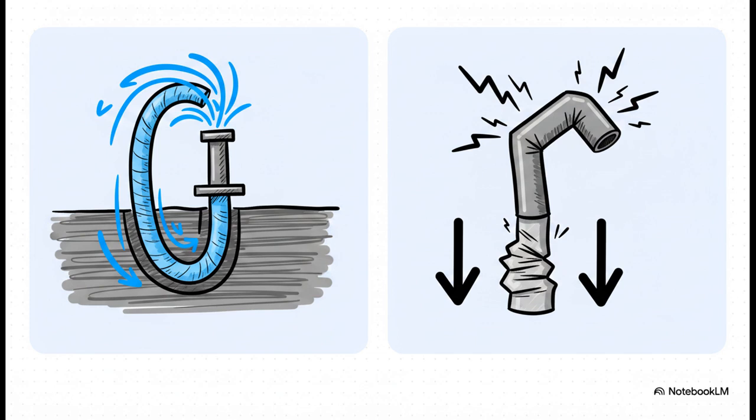But the cons? Well, bending solid steel onto a spool causes mechanical fatigue over time. The pipe can literally wear out and snap. Plus, pushing a thin, flexible tube into a high-pressure hole creates a pretty severe risk of the pipe buckling under compression, which puts a hard limit on how deep you can actually go.